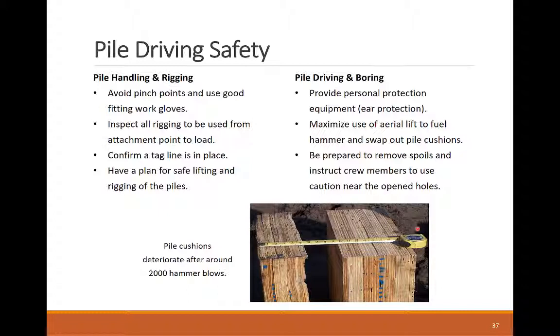Here are some safety precautions to consider during pile driving operations. When handling and rigging a pile, workers around the pile are under the risk of being hit by the lifted pile or getting their hands pinched or tangled with the rigging cables. So it's important to wear heavy-duty protective gloves and secure the piles with tag lines during their rigging time.